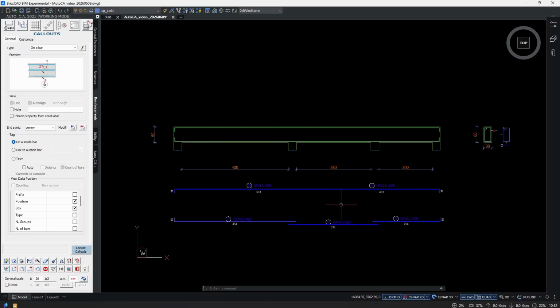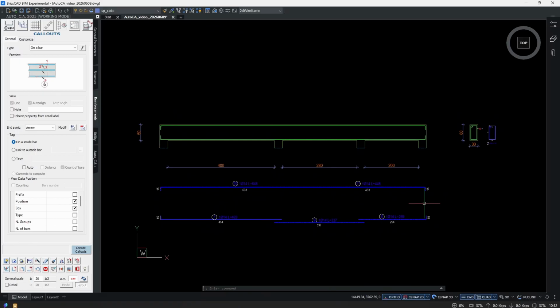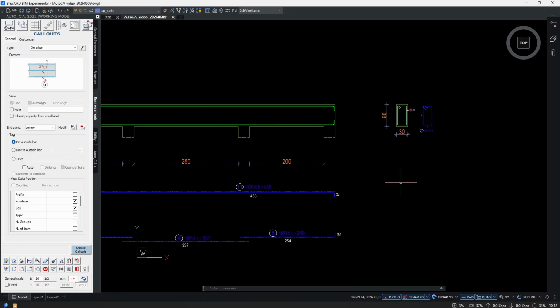What's the program logic? This is the most complex part of the program, which is actually quite simple. You must link the stirrups to the beam distribution and the longitudinal bars to the section bars. This is how the program calculates precise quantities. And again, I want to emphasize that these elements function as macros, so they are freely modifiable and reusable anytime.